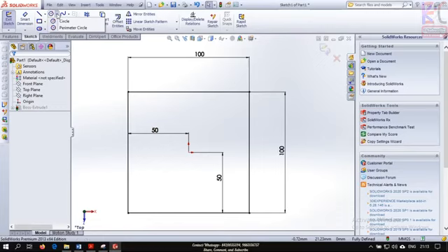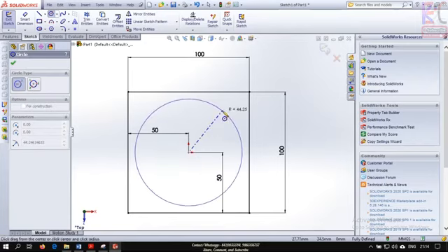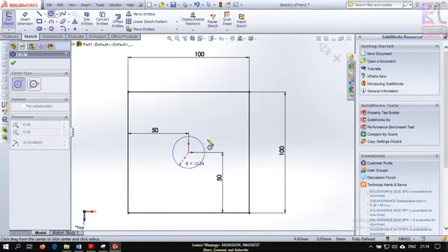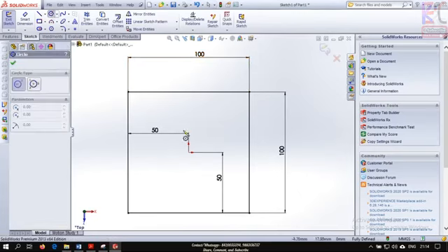And you could go from here, circle, fine, click over here. Now this shows the circle. When you bring it over here, you can see an orange dot highlighted, and you could see a cross section, a yellow point, showing over there. So you click over here and this just appears, fine. Don't keep clicking, click just once. After selecting the circle, click once over here, and release the key.